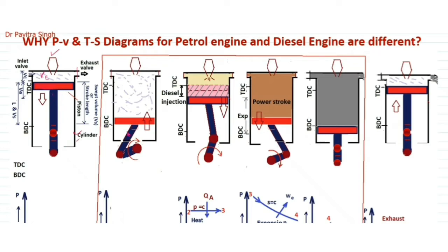The piston moves in a vertical direction, either upward or downward, so it is reciprocating, top to bottom and bottom to top, in all these figures. This reciprocating motion is converted into rotary motion by the help of the connecting rod, crank and crankshaft. So this device converts reciprocating motion into rotary motion.